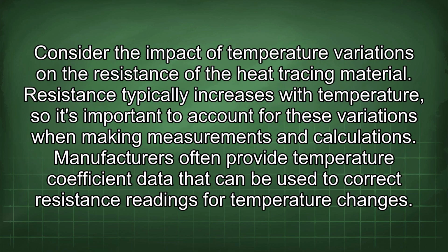Consider the impact of temperature variations on the resistance of the heat tracing material. Resistance typically increases with temperature, so it's important to account for these variations when making measurements and calculations. Manufacturers often provide temperature coefficient data that can be used to correct resistance readings for temperature changes.